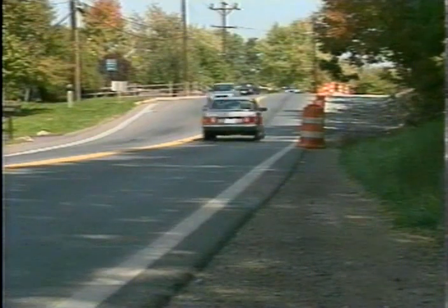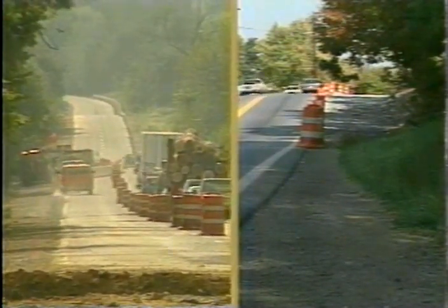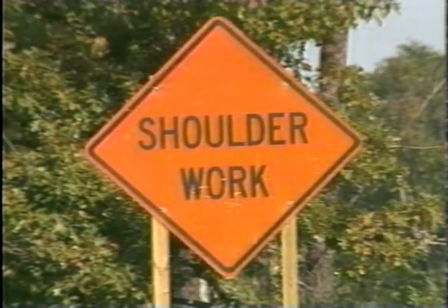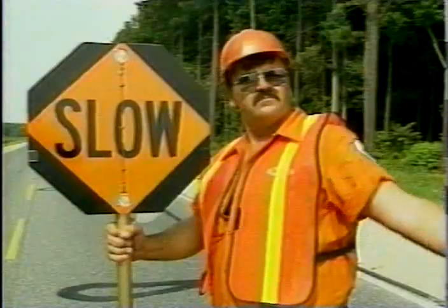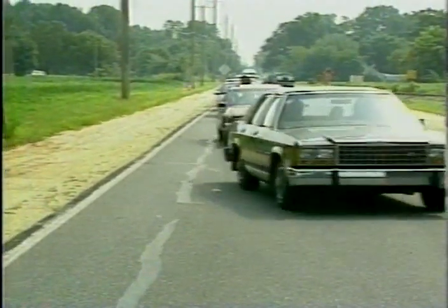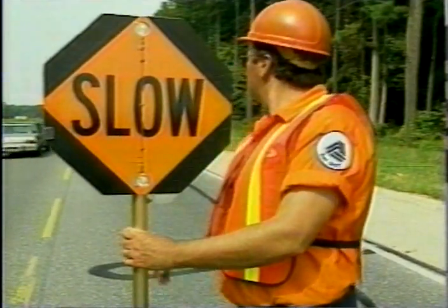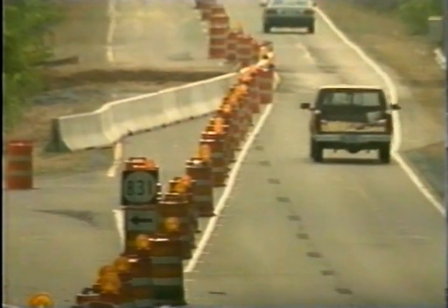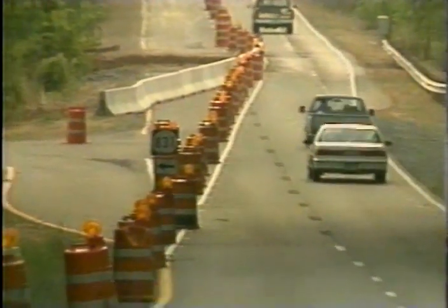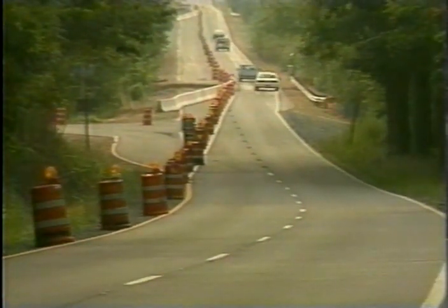There are 2 types of work zones: shoulder operations and lane closure operations. Usually, a single warning sign or vehicle warning lights are enough. A closed, improved shoulder requires a taper of channelizing devices. Work that closes off lanes of traffic falls into 2 categories: closing off 2-lane, 2-way roads, and work on a 4-lane, 2-way road closing at least 1 lane.